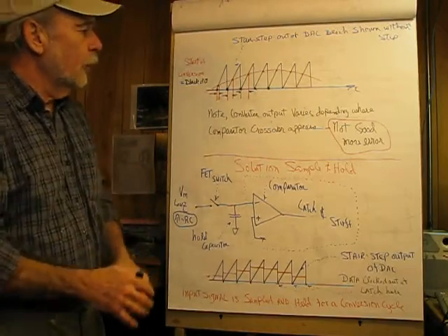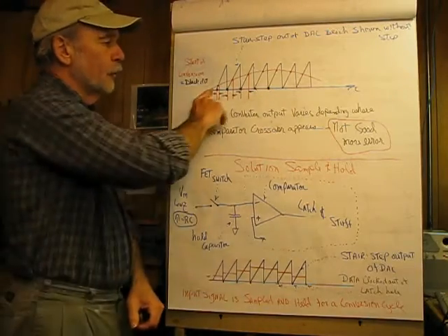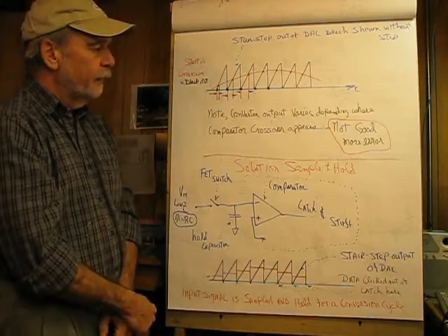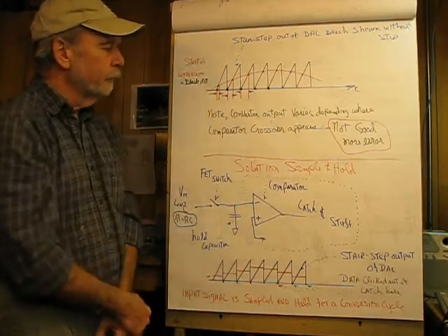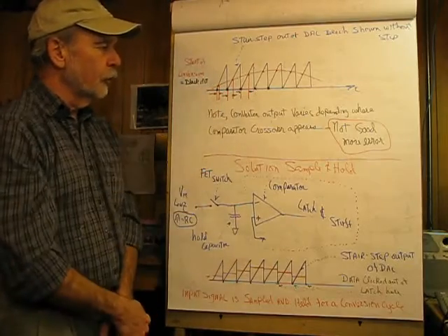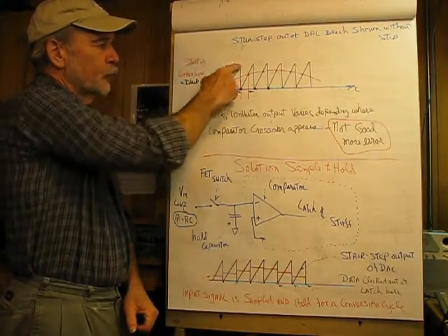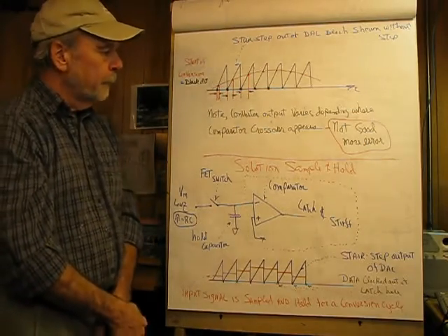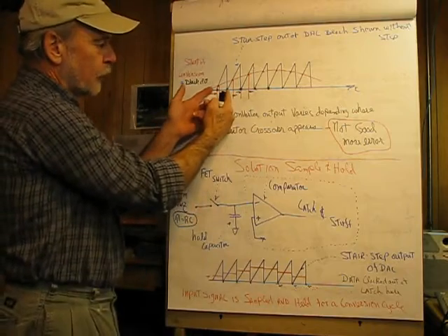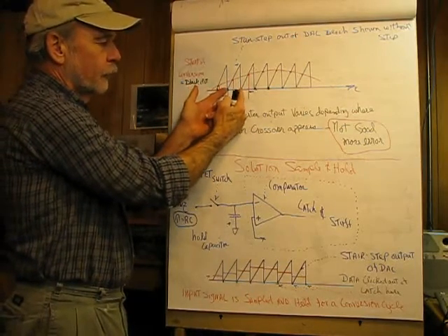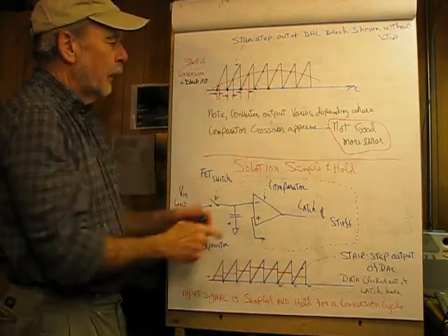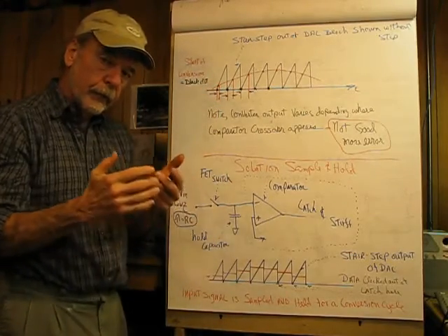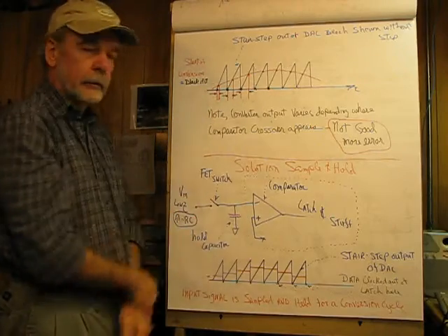So in this, I'm showing the input voltage V varying, like perhaps the top of a sine wave, and I've taken our 16 steps including 0 here, and I'm running them up, just showing them as a straight line so I don't go through the tedium of trying to draw the steps. And what we're seeing here is that between the black dots is one conversion cycle. Here, it didn't have to count up very far until the output of the stair-step generator crossed the input.